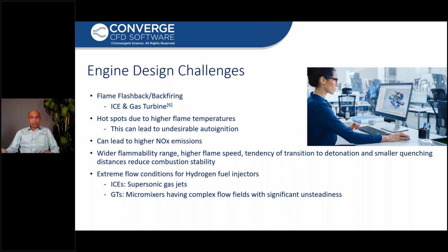Exhaust gases can also backflow towards the intake manifold during valve overlap in hydrogen port fuel injection engines, which can also create a risk of flame backfiring. During fuel changeover of gas turbines, flashback of the flame into the fuel injector at higher hydrogen concentrations can occur.